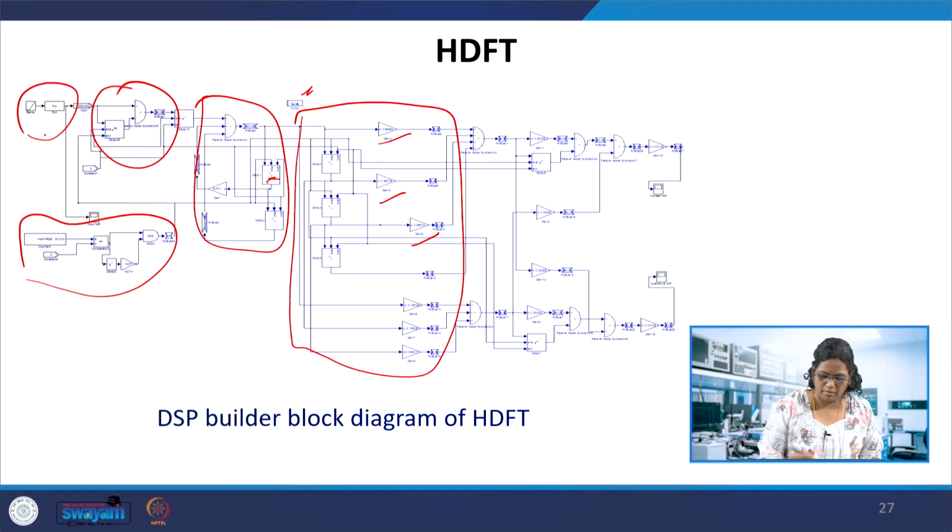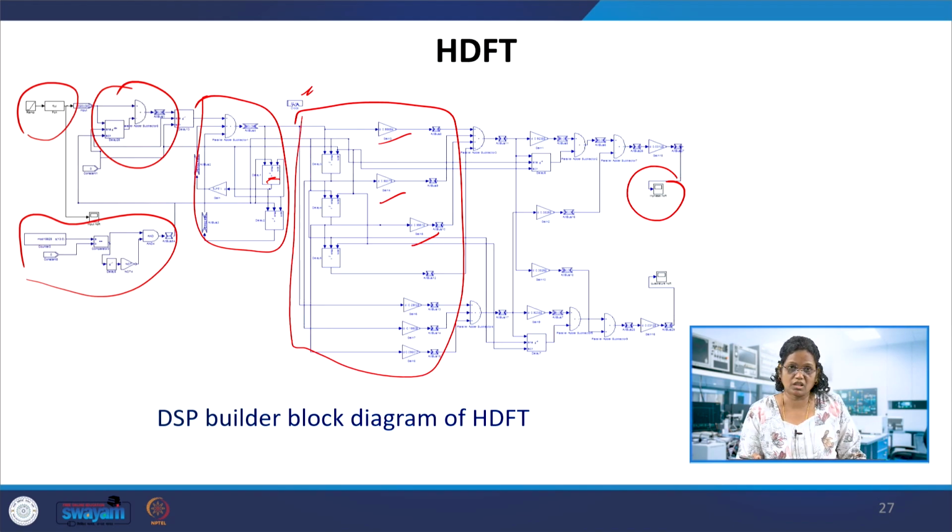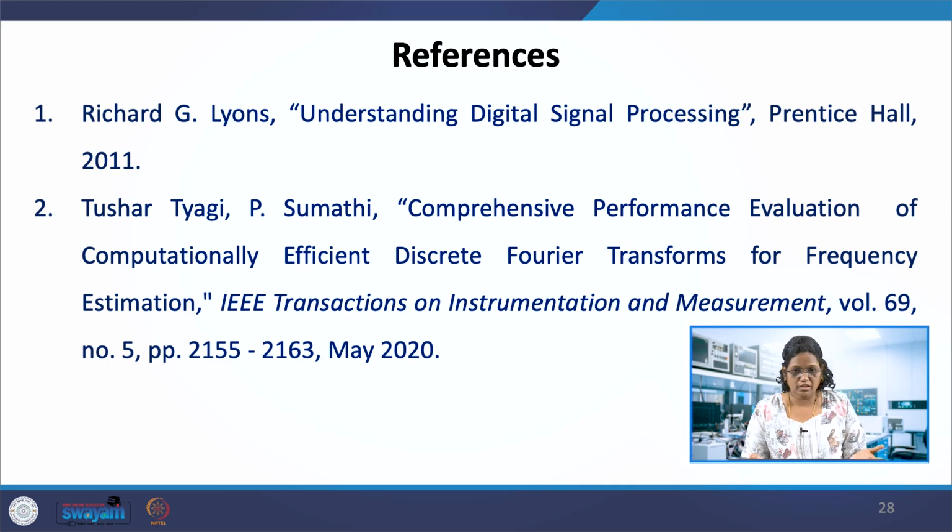Here I have not connected the inputs. Similarly, the inputs are taken from MATLAB, and this scope is the MATLAB output, but in real time an ADC and DAC are to be connected. We give the input through the ADC, and this whole blue block will be in the FPGA, and through the daughter card the ADC input signal will be fed and the output signal will be taken out through the daughter card of the DAC. So we will show that in the real-time demos, and those things can be learned.